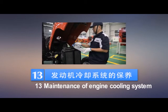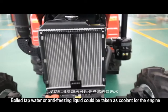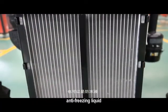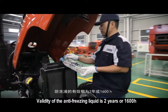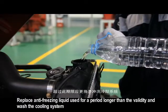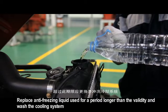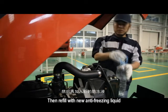13. Maintenance of engine cooling system. Boiled tap water or anti-freezing liquid could be taken as coolant for the engine. Validity of the anti-freezing liquid is 2 years or 1,600 hours. Replace anti-freezing liquid used for a period longer than the validity and wash the cooling system. Then refill with new anti-freezing liquid.